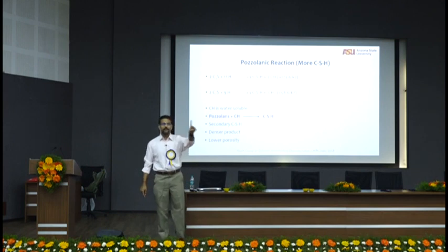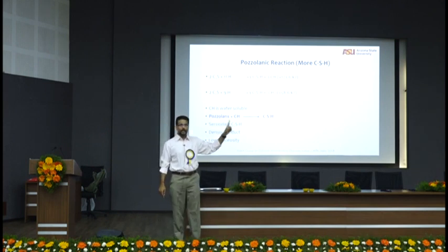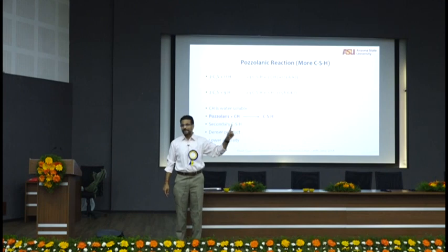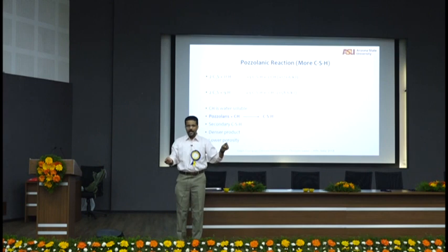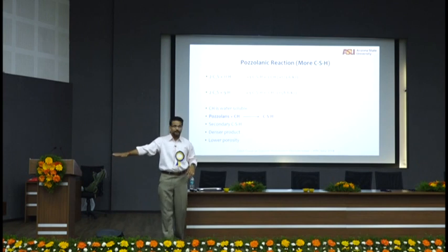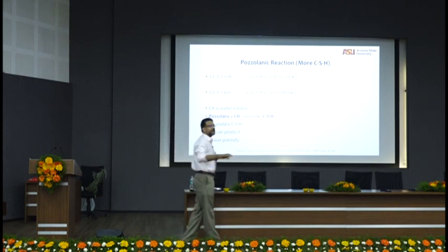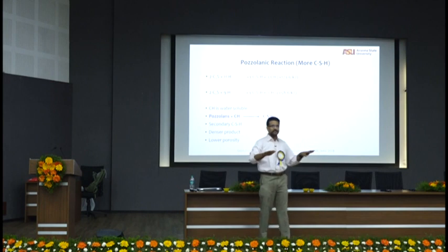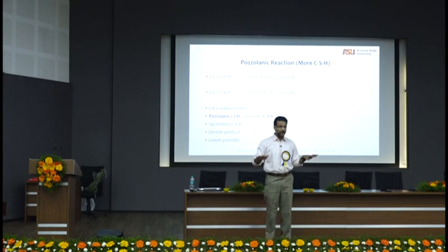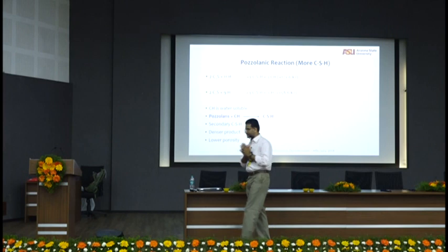Unless, there's one caveat to that rule, unless you dump a lorry load of silica fume. Silica fume will eat up calcium hydroxide very quickly because silica fume is telling, I'm really fine. I don't need anything else. I'm this reactive silica. You show me calcium hydroxide, I'll immediately react with it. I don't need an external medium for me to help you. See that? So if you have a lot of silica fume, you can deplete calcium hydroxide. Depleting calcium hydroxide with fly ash is a researcher's dream. It's an utopian dream. You will have calcium hydroxide in a system with fly ash.